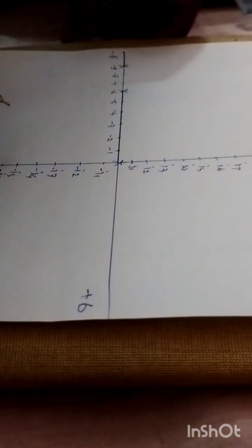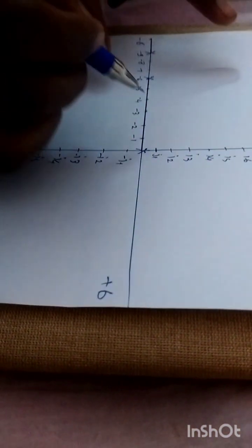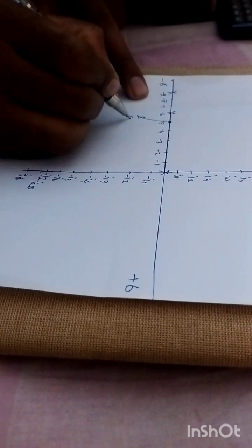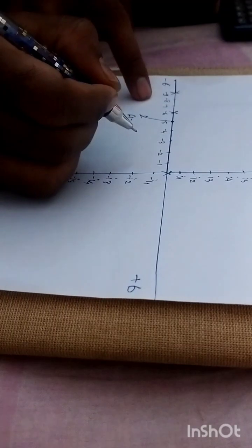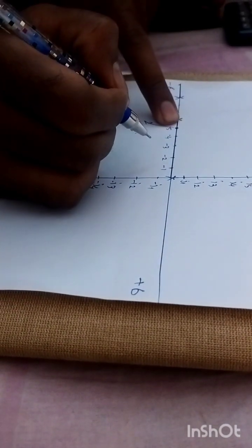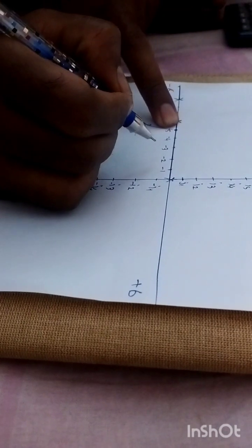After that, as we know, the centroid of this loci, sigma c, equals how much? It is minus 5, right? So consider sigma c equals minus 5. With this sigma c, with the help of a protractor, we need to plot the angle of asymptotes, right?